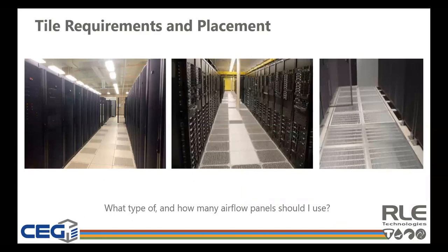And I've been in many data centers where way too many airflow panels have been placed in cold aisles when compared to the actual IT load, kind of like the picture there on the right side of the slide. The assumption being that more is better. And overcooling a cold aisle is definitely inefficient and is also detrimental to preserving floor pressure, which in turn requires more fan power usage from the cooling units and therefore higher cooling costs.